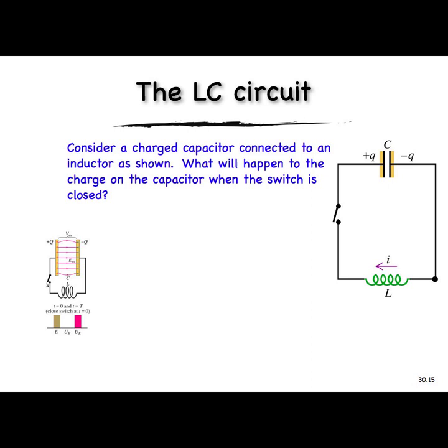So put the I's on the left side, the t's on the right side, just like I did before, and then I can integrate both sides. But now if I start at time 0 and I go to time t, I'm assuming that my initial current is not 0, but rather some value I naught. And I'm interested in finding little I, the current after some length of time.